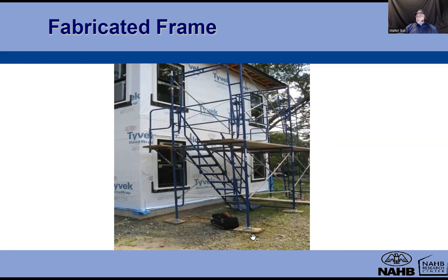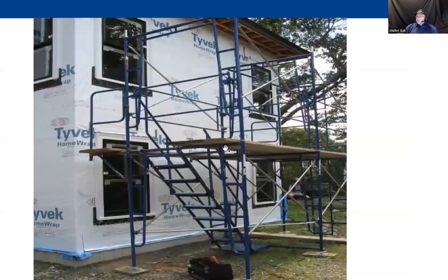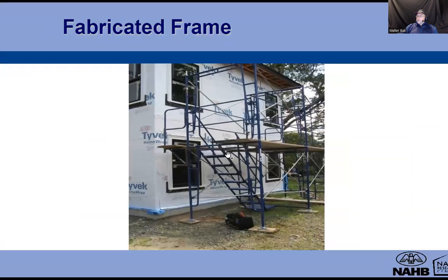You can see that there are some mud sills, there are cross braces right here to keep the structure in place. You can see the platforms sticking out far enough. Do I see any cleats? I don't see any cleats, but there could be hooks that are provided to keep things in place, so that probably will be fine. This is a correct way of setting things up.